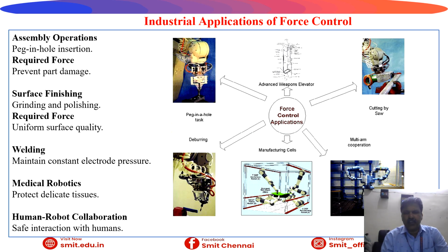Now, various industrial applications we can have a glimpse of in this slide. Assembly operation, first of all: peg-in-hole insertion, requires force control to prevent part damage. Surface finishing, grinding and polishing: requires force control for uniform surface quality. Welding: maintain constant electrode pressure.